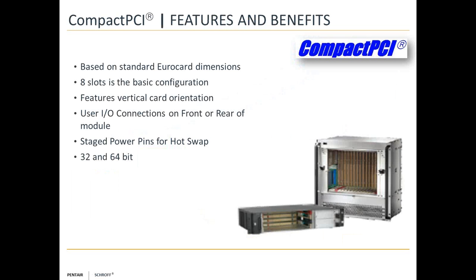Okay, starting off with Compact PCI, it's based on a Eurocard 3U and 6U form factor and supports 19-inch mechanics. Compact PCI provides a passive backplane up to 64 bits and 66 megahertz. It connects the system slot or the CPU to up to 7 peripheral slots or devices, or more with bridges. The original architecture is based on a parallel bus, which connects the system slot to the peripheral slots. The backplanes are available in 1 to 8 slots. However, it is extendable by bridges up to 21 slots.